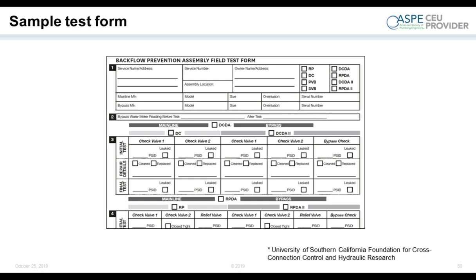On type 2, I have a question. I don't understand how the first 2 gallons pass the bypass when both the bypass and the main assembly number 2 checks have the same pressure drop. Okay, that might have just been an issue with the numbers that I put up on the screen. The pressure drop across the main valve second check should be higher than the main valve bypass single check.